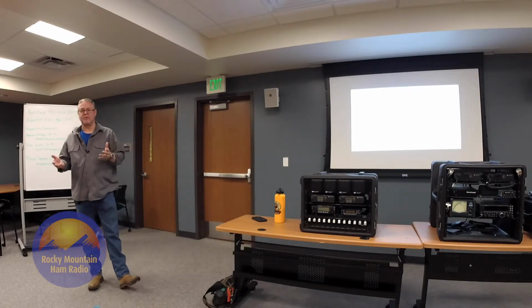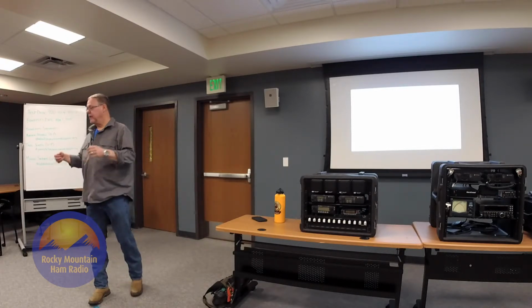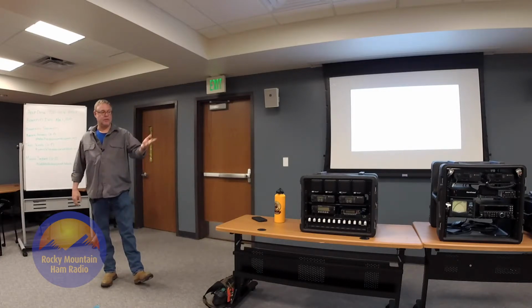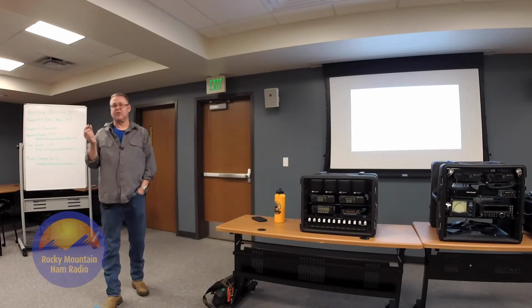I use blue and yellow or whatever color. It doesn't matter as long as it's not black and red, so I don't accidentally hook power to it. And I know if it's a color other than black and red, I can connect them together. They can be used for a wide variety of other things because the power pole does not have to be just 2 connectors wide.